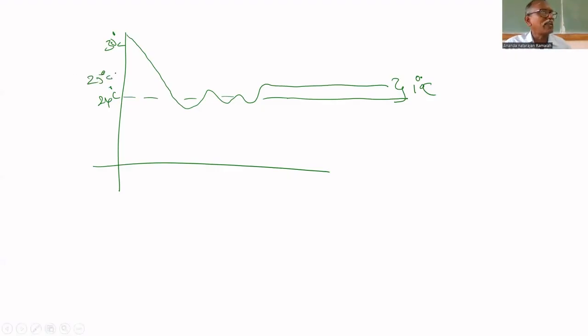It never comes to 24, because to make that P controller functional, it needs error. That's why it will make 25 only. For example, I am telling 25. There is a calculation. At that temperature, it will maintain. But never 24. So P controller also failed.